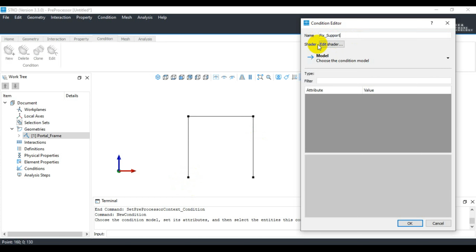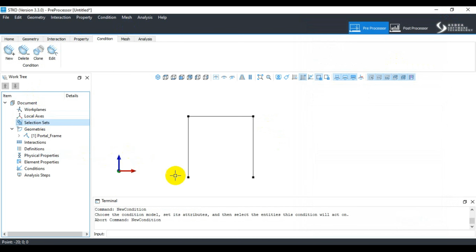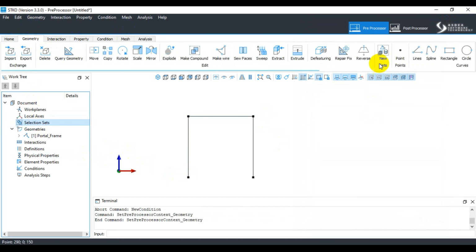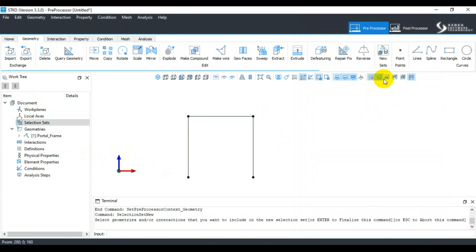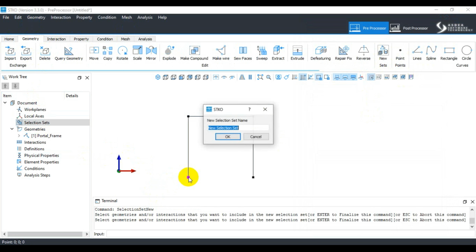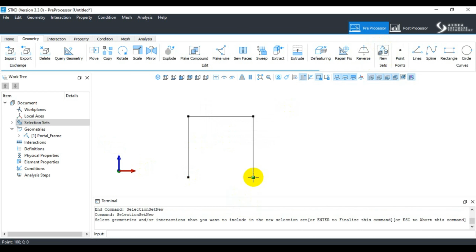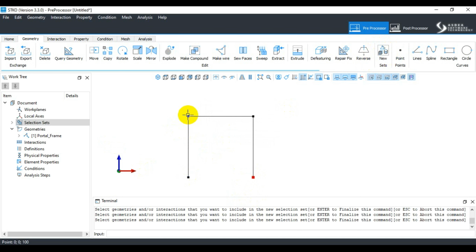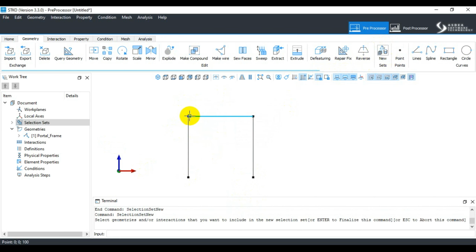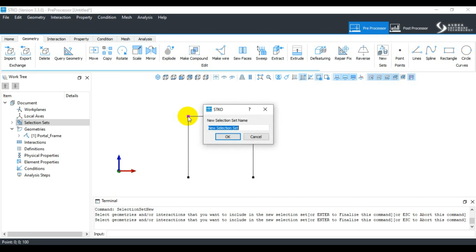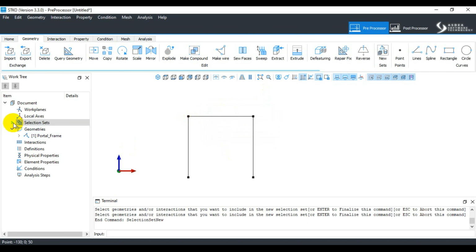A very professional way to consider this is, for example, if I go to home and make it more sensible, let's switch off these options and leave only the vertex command and call it node A. Similarly, doing it again, select this one, press enter, and call it node B. Click on OK, and we got this here.